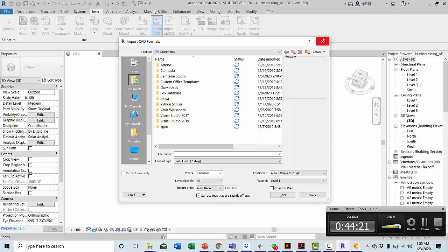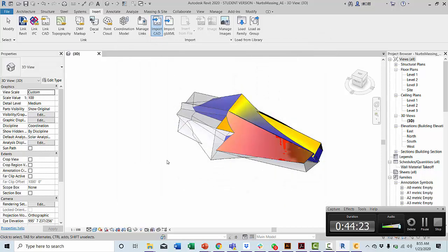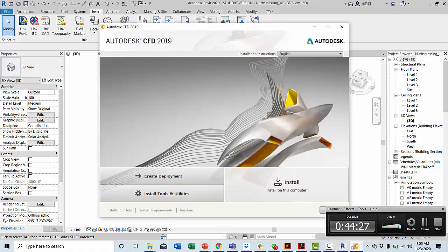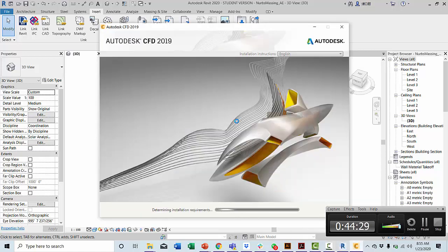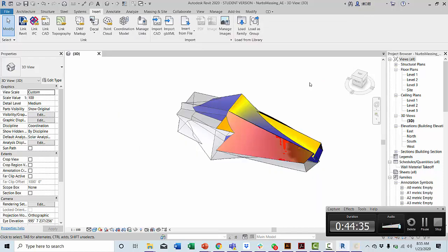Another thing, if you're going to use the topo surface or the site for Revit, it's better if you use their own system. They want you to use the topography tool that they have. With that, you can shape the ground, or whenever you put a section, you will see the ground hatch. It's easier for you to specify the different spaces.